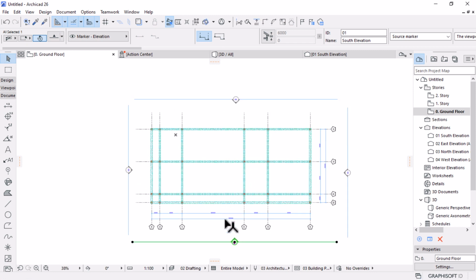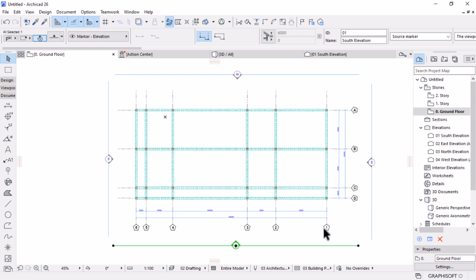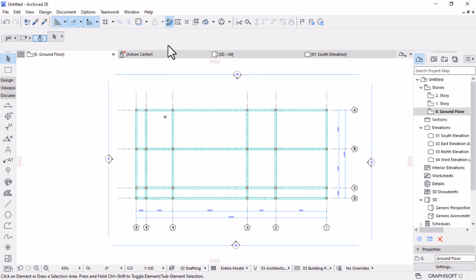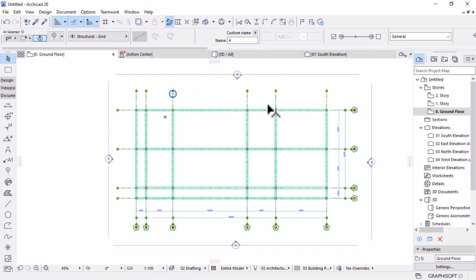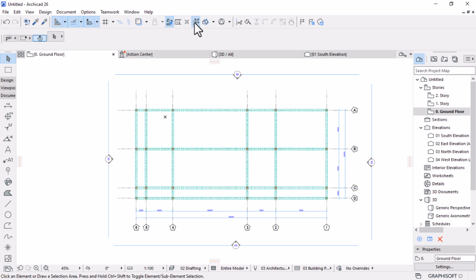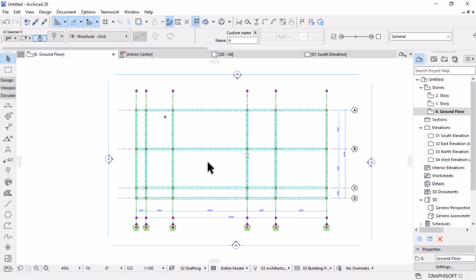Okay, I wanted to have this marker positioned at the top. I could just select that, but make sure, because by default ArchiCAD, when you place this kind of elements in groups like this, they will be grouped by default. As you could see, if I select them, they are all grouped. What you need to do is activate the suspend groups here, or Alt G to ungroup, so that I can select this vertical line separately. And then I could say Control M. I would use this center to mirror.